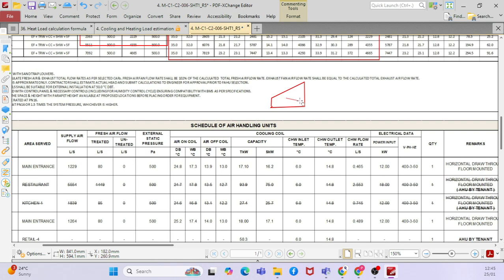You can plot it here, assume, right? Yes, sir. When you go to the dew point temperature, you will reach this position. So what is the dew point? It is when your dry bulb temperature and wet bulb temperature are at the same reading. That means your air is saturated.